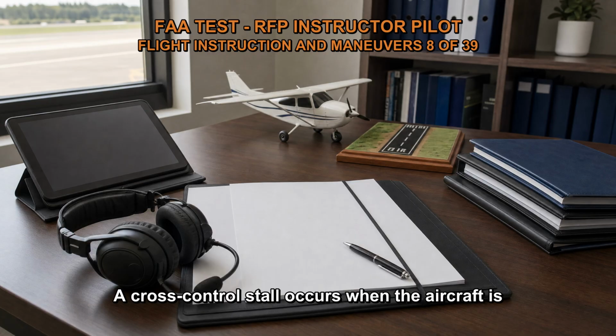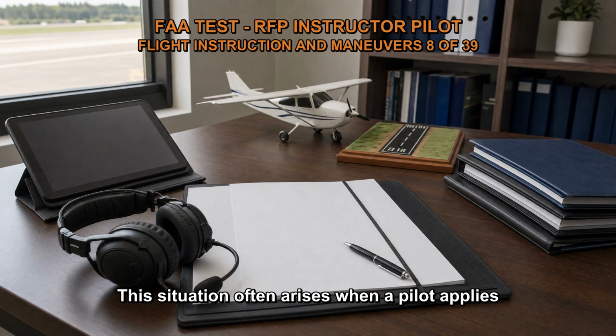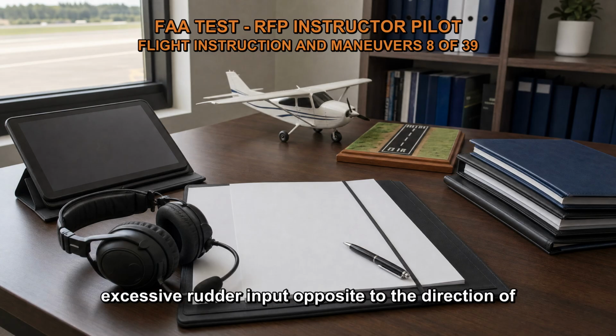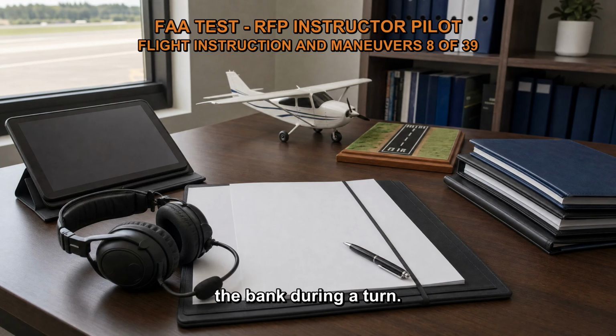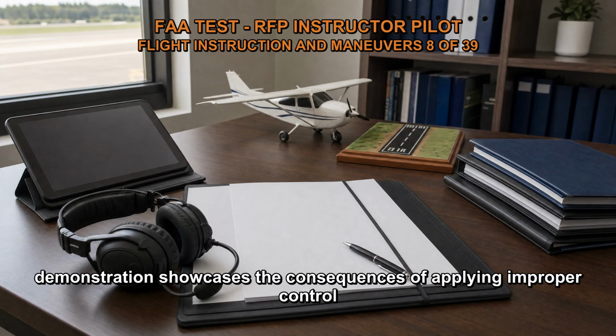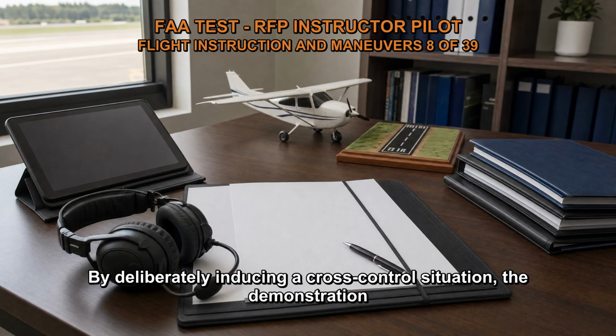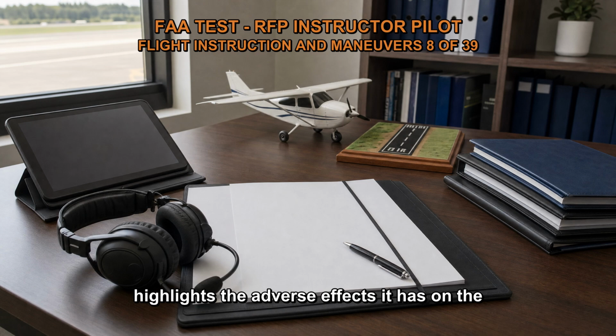A cross-control stall occurs when the aircraft is in a stalled condition while the ailerons and rudder are applied in conflicting directions. This situation often arises when a pilot applies excessive rudder input opposite to the direction of the bank during a turn. Effect of improper control technique. A cross-control stall demonstration showcases the consequences of applying improper control inputs during turns. By deliberately inducing a cross-control situation, the demonstration highlights the adverse effects it has on the aircraft's stability and control.